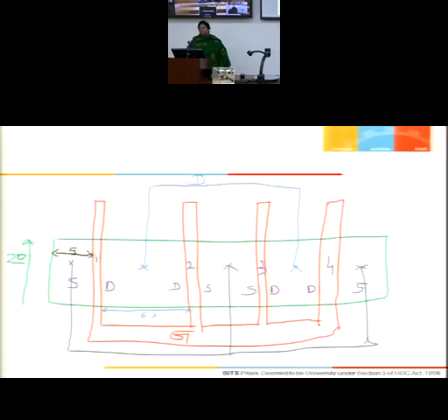This also brings in the other methodology of making a bigger component by using many small components. So where does this strategy, making a bigger component by using small components, also help us in controlling the W by L ratio of the two matched components.